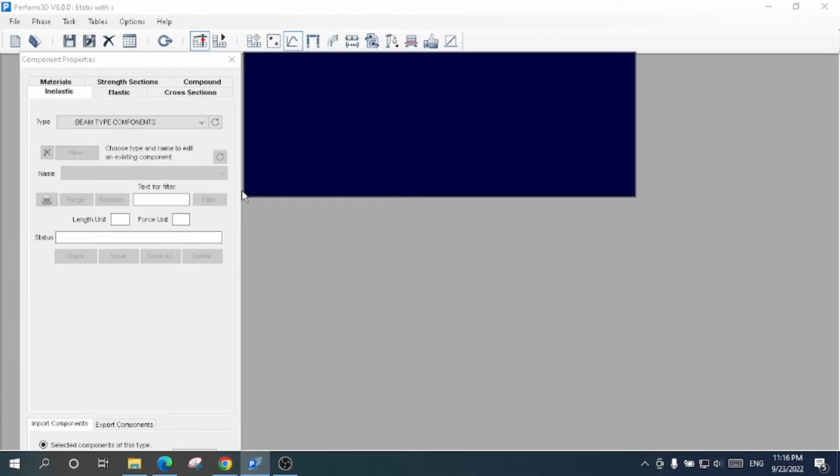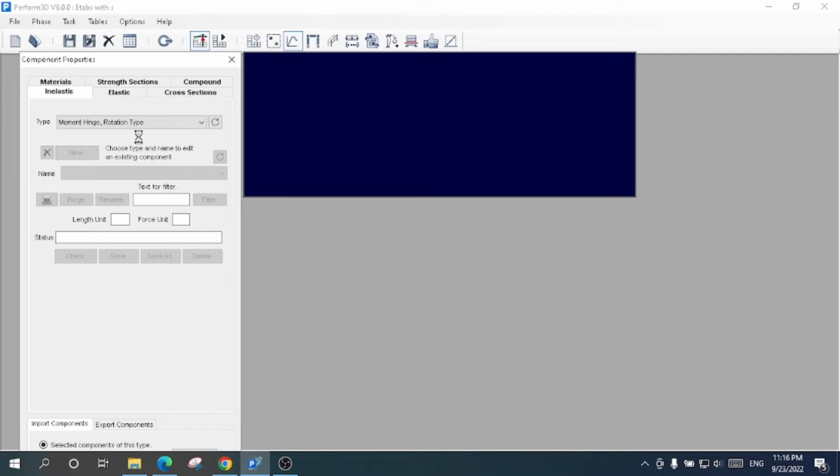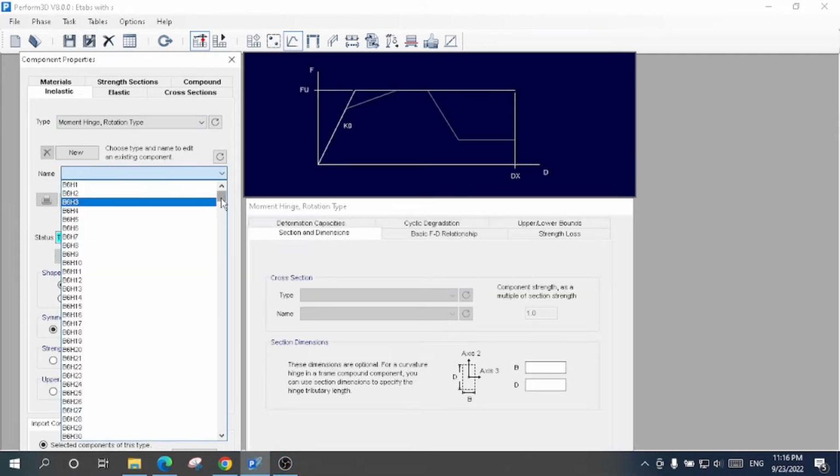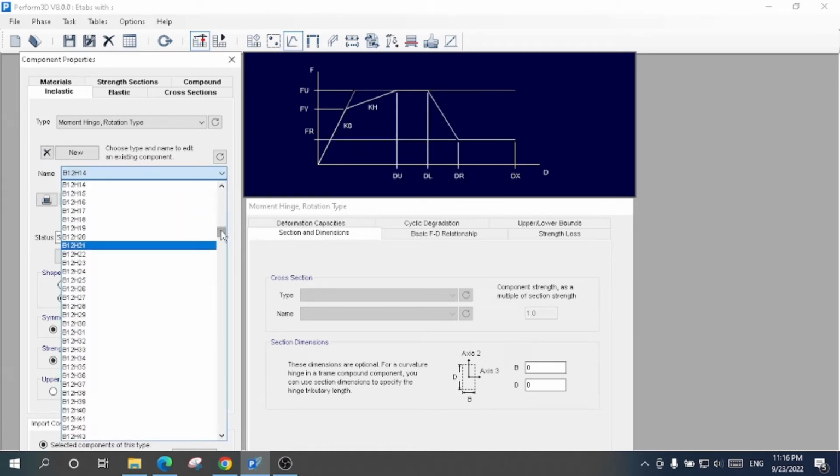For inelastic, I will come here to the beam sections or column sections, where I will define a moment rotation. These will be taken from, or assigned in, ETABS, so there is no need to define all these moment hinges. Define and assign all these rotation type hinges in ETABS; it is simple and automatic. Here is a very big problem.